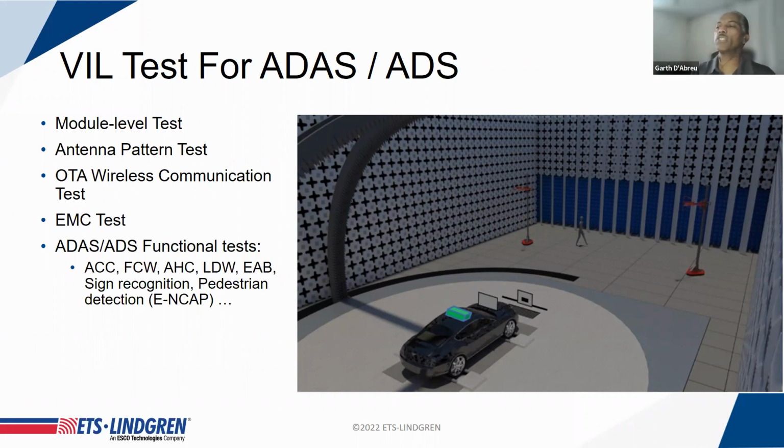Several of the manufacturers, as I said, have setups based on video screens in front of the camera system, radar target simulators in front of the radar module, and the vehicle driving on a chassis dynamometer, again, under controlled, predetermined driver scenarios. And then you would bombard that environment with the immunity environment. And again, make sure that if you tell the car to drive at 100 miles an hour and follow about 300 meters behind a very large bus, then it'll continue doing that under all of the interfering conditions that you can throw at it.